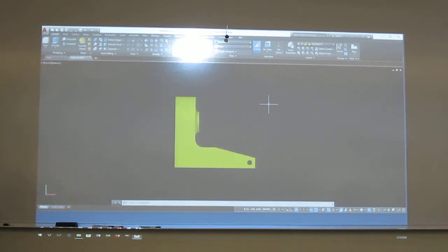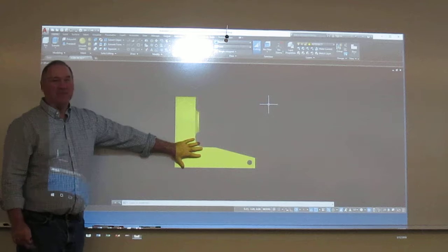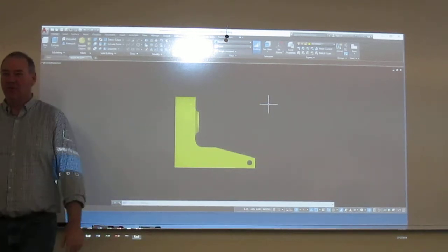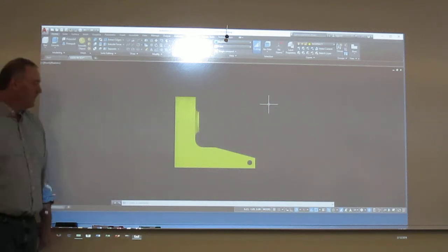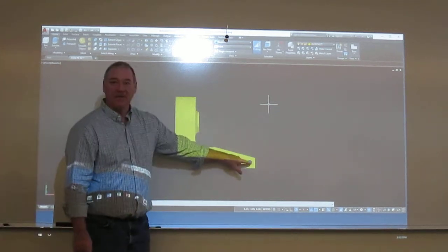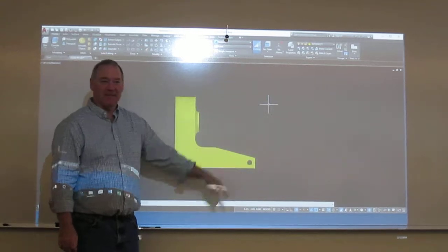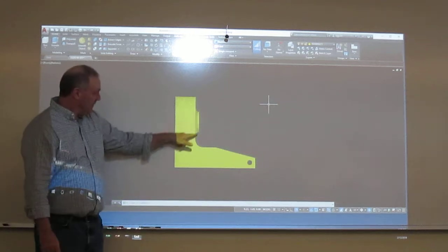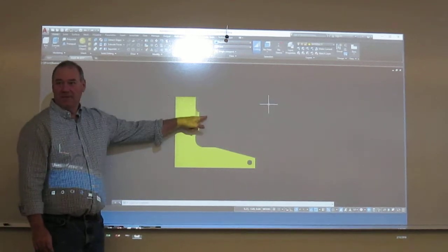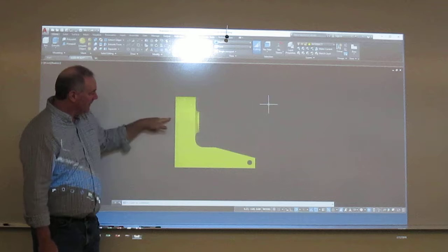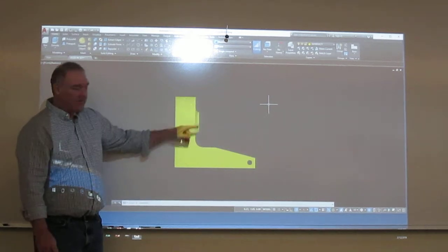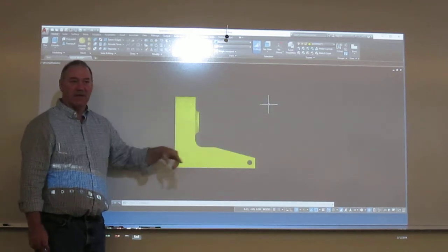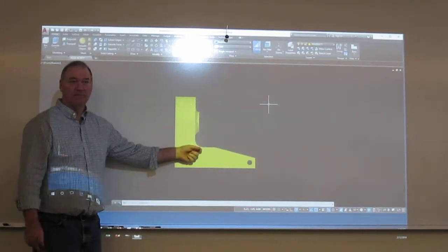Okay, so I look at this guy, and I say, okay, here's my front view. This is a pretty good orientation for a front view. Is it a 3-view drawing? What's described here? Well, I need it for this hole right here. I've got to give a circular view of negative cylinders, right? I've got a positive cylinder right here. That will be dimensioned in this view. I've also got a negative that comes through here I don't see, but I do get height and width of all my features. I don't even see the slot. Okay, so this is probably one view.